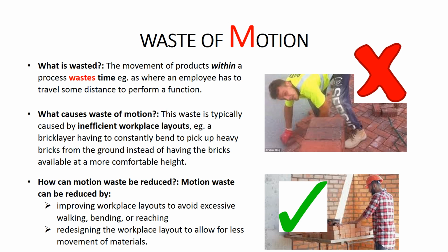In the video that you watched about the Toyota motor manufacturing facility in Kentucky in the United States, we saw one way of reducing motion waste. This was the removal of the doors from the cars during the assembly process. This reduced motion waste caused by workers having to walk around those doors and to open and close those doors while they were installing components.